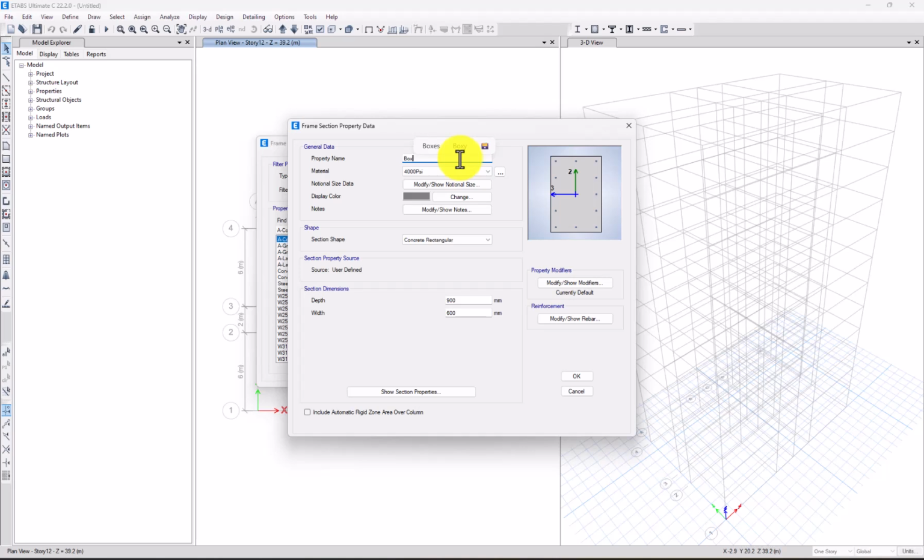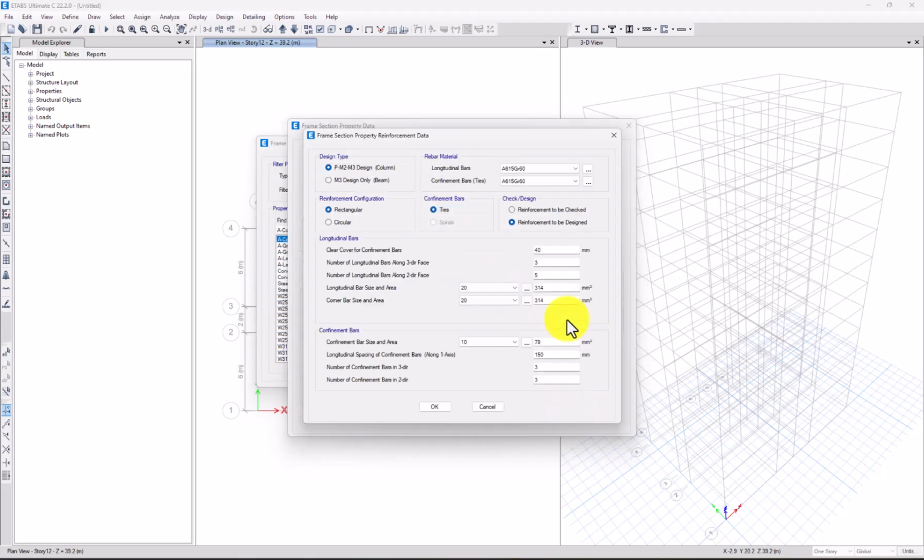or let's say box or square sections. It's going to be 80 by 80, which is 80 by 80 centimeters. So I'm going to call it 80, and this will be 80. Additionally, I must choose the concrete material here. Use 6,000 psi, and for the reinforcement, the reinforcement grade is 60.